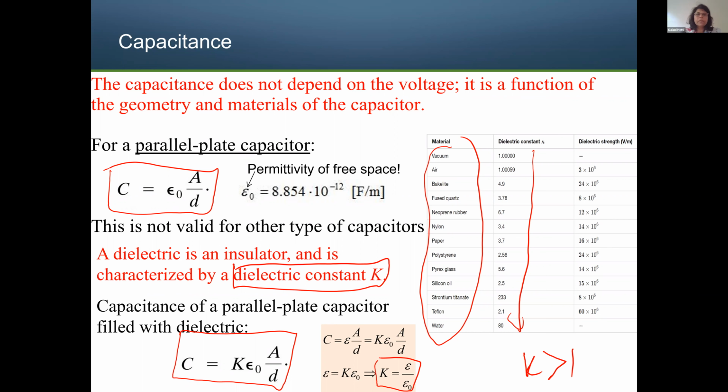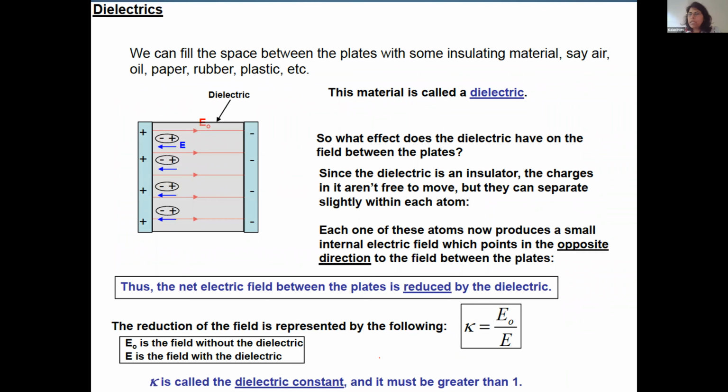Now, dielectric media a little bit. Dielectric means basically insulator. If I have an insulator in between these two plates, the insulator cannot carry the charges. So how are you going to charge this? When I have insulating media, these charges basically stay together. There is no way you can separate those charges inside the insulator, the non-conducting media. Because of this charge separation, or charge polarization, they will create a small electric field that I have in this blue color.